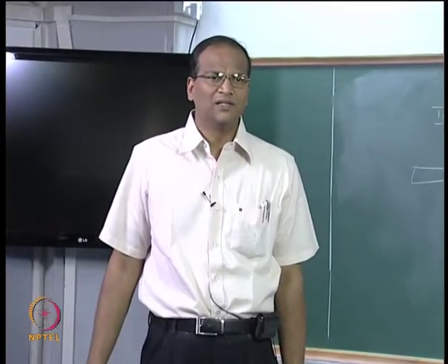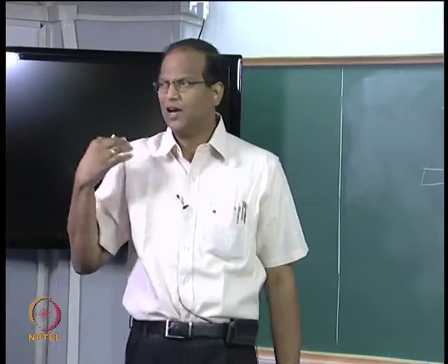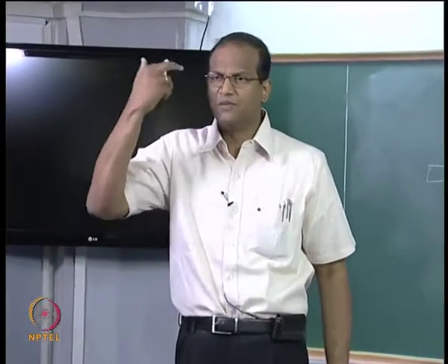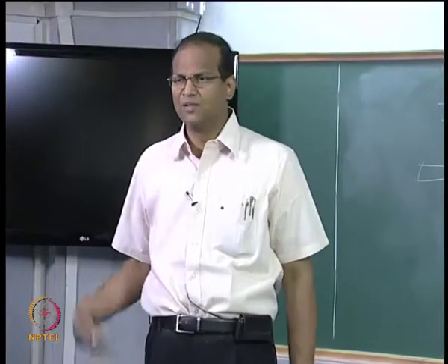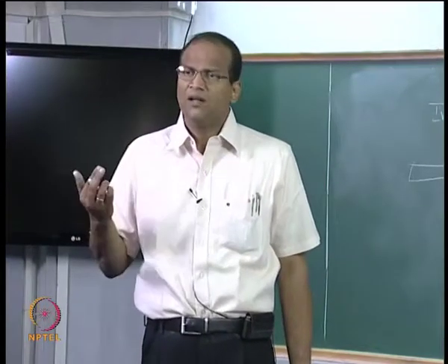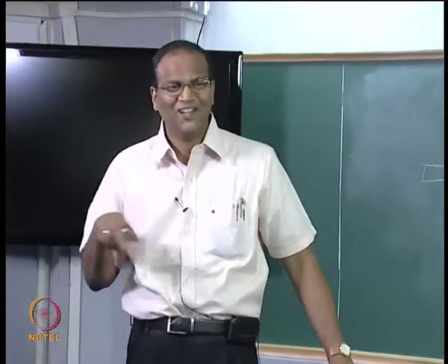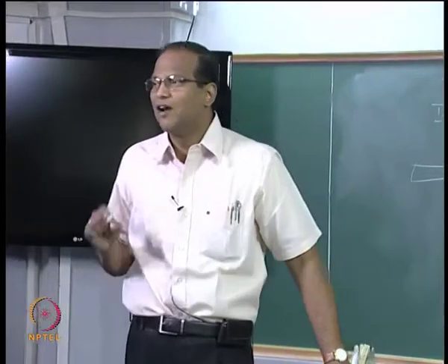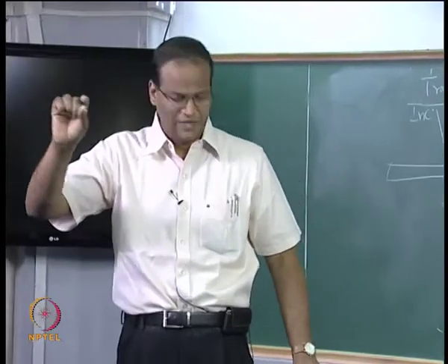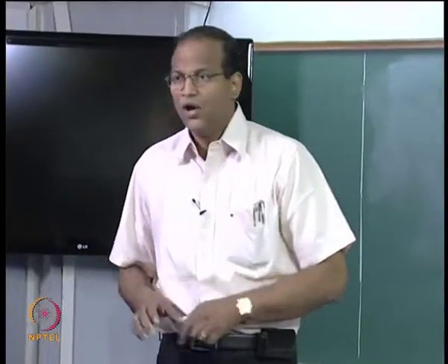An opaque surface has tau equal to 0. If it has 100% transmittance, tau equals 1. For example, glass: some surfaces will have 90% plus in certain portions of the spectrum. And just like emissivity, absorptivity and reflectivity, this fellow can also misbehave. It can vary with respect to lambda and theta, so it can lead to complexities. But we are talking about thin media: a thin layer of glass, a lens or a prism or a filter, or the atmosphere.